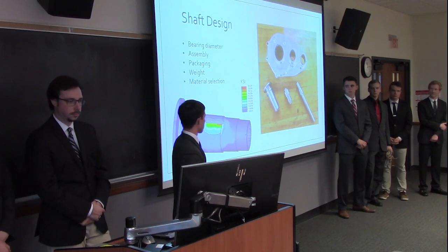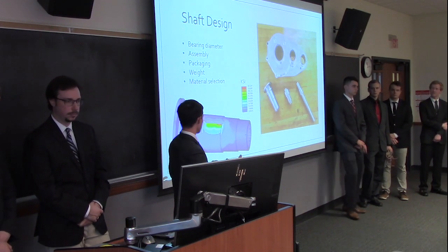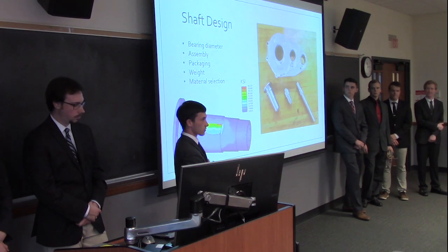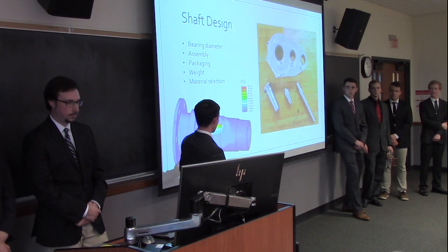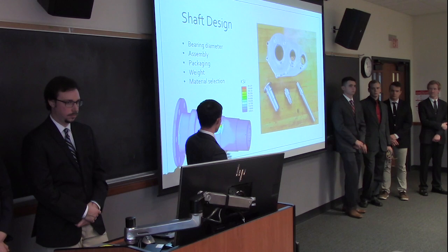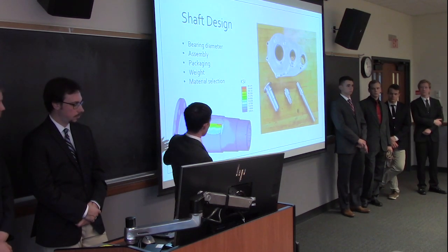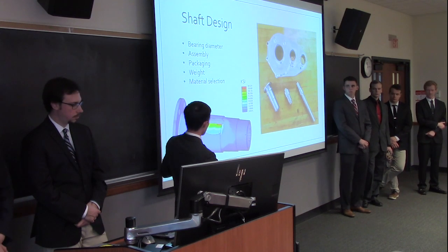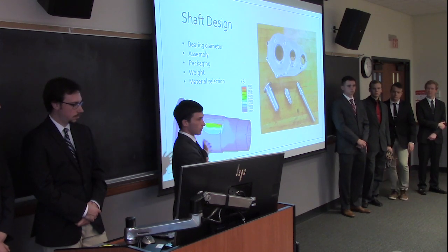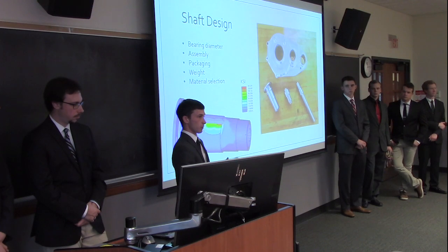Other considerations that went into shaft design were where everything had to sit on the shafts. You're oftentimes press fitting many different components on. So all of your bearings, your gears, and in this case a brake disc all have to slide on properly and need to be located so that they can't walk back and forth through vibration.